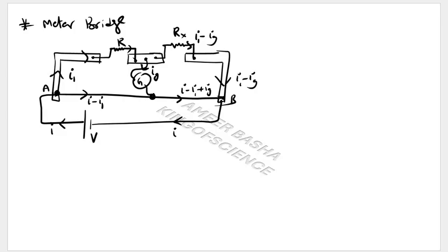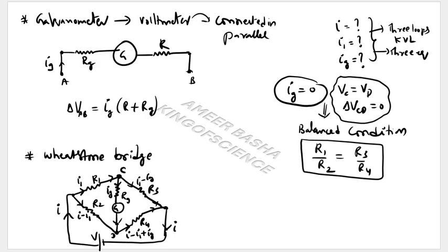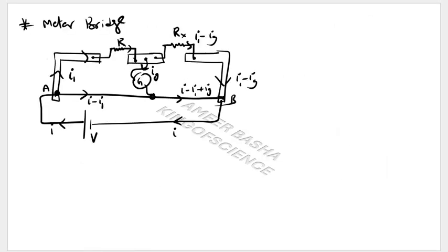So it is exactly almost like the Wheatstone bridge. These are the A and B points, and this is my C point and this is my D point. Now AD is the resistance of AD. That is the balanced condition I am writing. The known resistance R divided by the resistance of the part AD equals the unknown resistance Rx divided by the resistance of the part DB here.